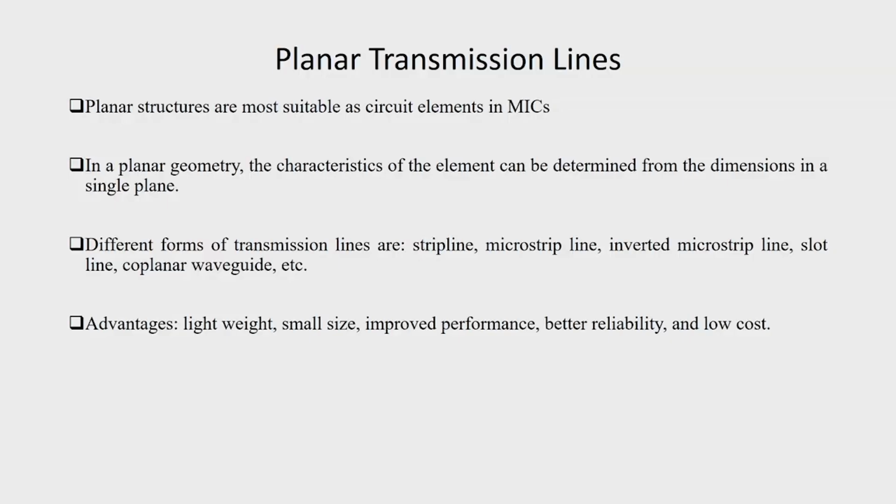So, planar transmission lines have the advantage of being lightweight, smaller in size, providing improved performance, reliability is often better, and cost wise also it is low cost. They are also compatible with solid state chip devices. So, compatibility becomes an issue when we talk of microwave integrated circuits.